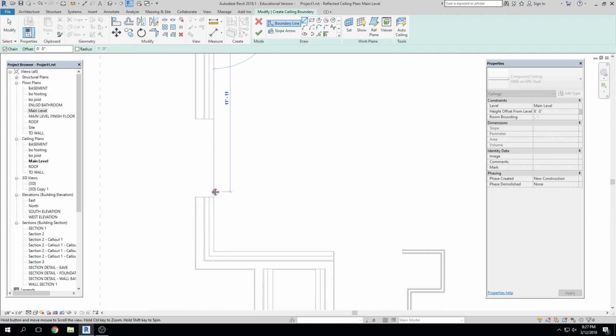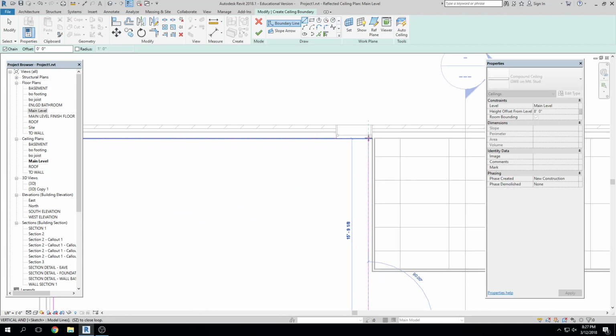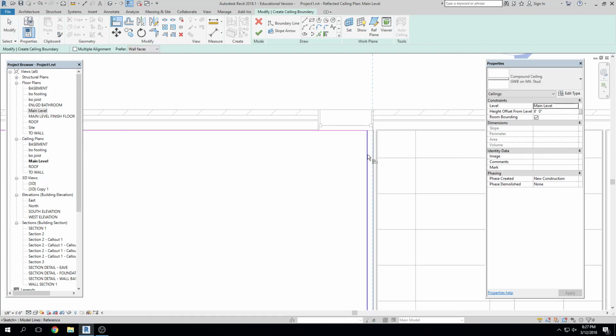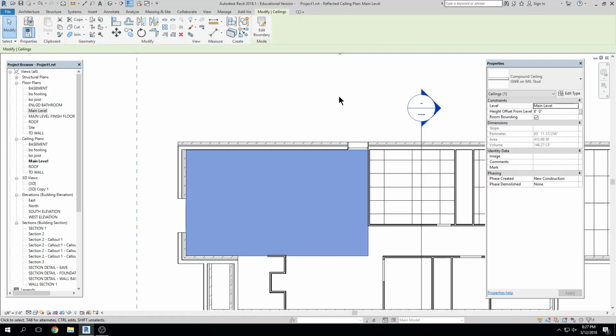Now, again, ceilings are a lot like floors. So I'm just going to draw one squarish ceiling here that doesn't trim, TR, click, click, AL, align, click, click. Okay. I'm going to hit finish. There we go. There's my ceiling, right? Ceilings are just like floors in that if I want to leave a region out, I can.